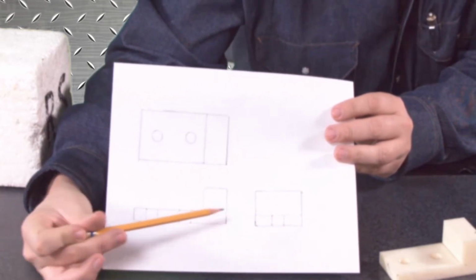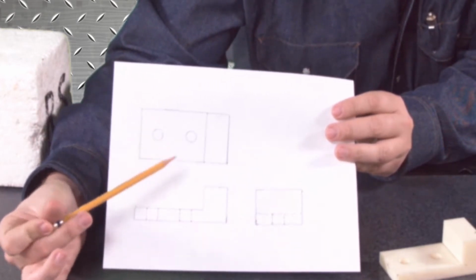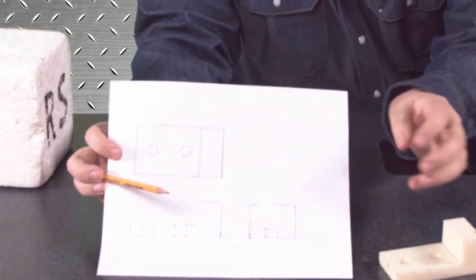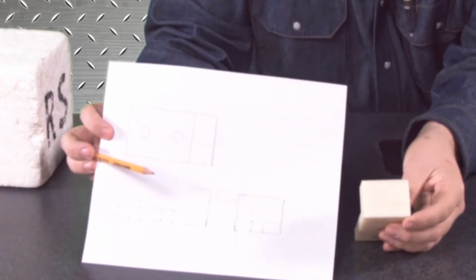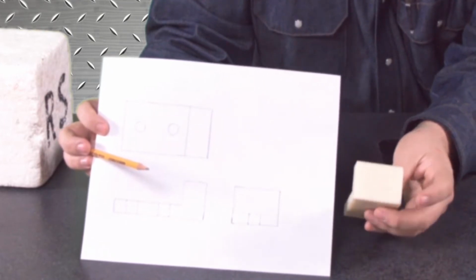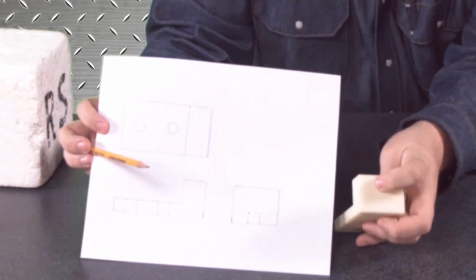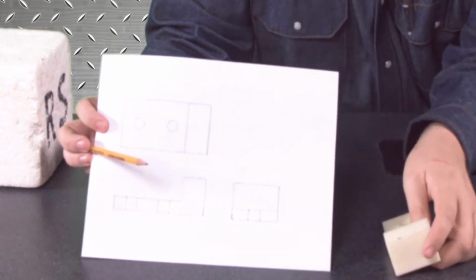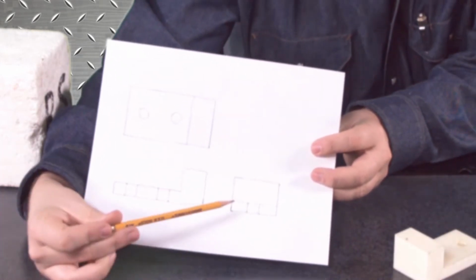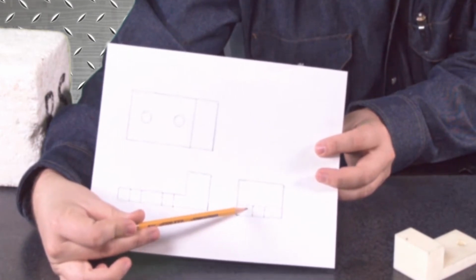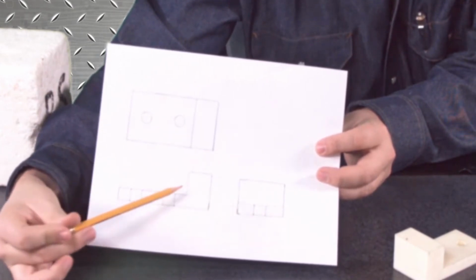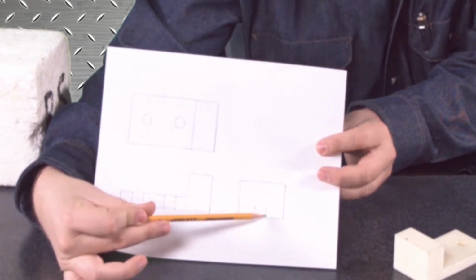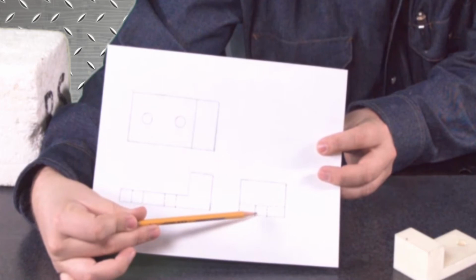Now, onto our top, this is our front side, and this would be our right side view. Now, the right side view, if you were just to see this as a visible plane, all you see is just this one rectangular plane right here. But you can also see I've got a hidden line representing the other plane that exists behind this from where this extends up. And then you've got hidden lines here for where the holes are that are drilled through this part.